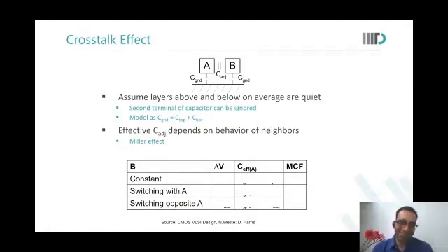Okay. And sir, another thing you mentioned was about the number of contacts when we were modeling a certain width of PMOS or NMOS, and how we should be careful not to overkill, right? When we reduce the number of contacts, I understand how that would reduce the capacitance between the poly and the contact, but how will that affect the resistance exactly? I didn't get it. So see, contact resistance, let us say, is 10 ohms. And you made 10 contacts. So resistance became 1 ohm.